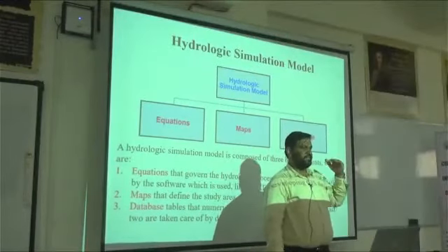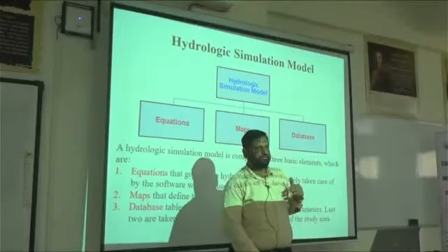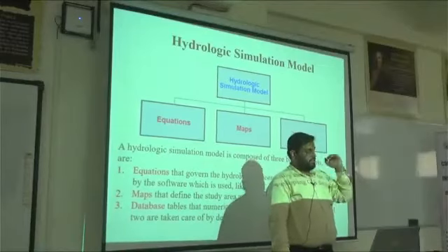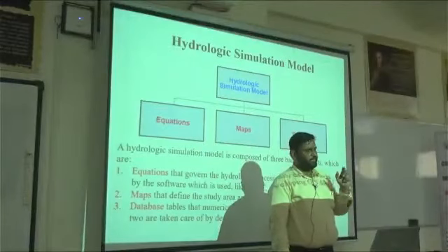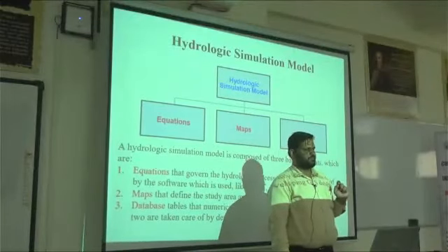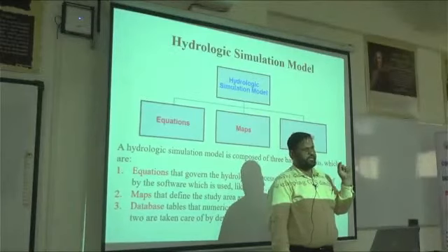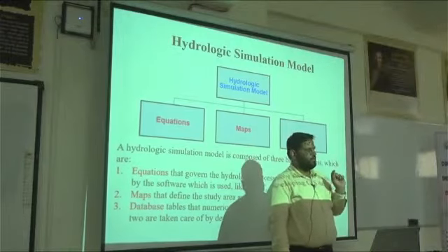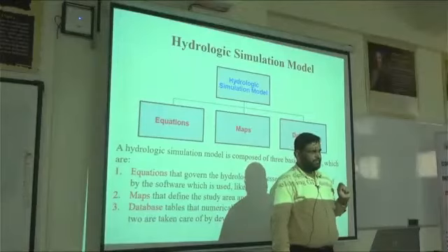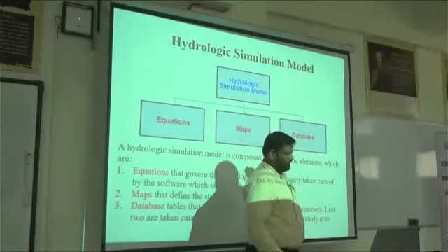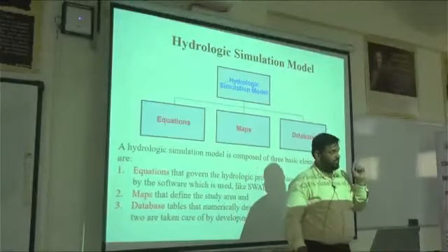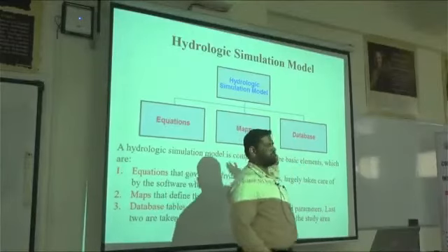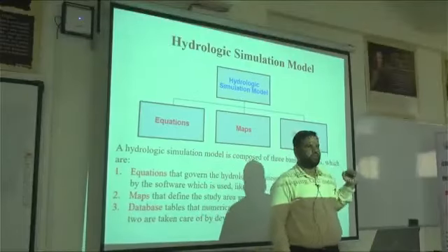The understanding of those parameters is very important, because simply developing a hydrological model is not a very big task, but doing a calibration is a very tricky as well as tedious task. Unless you have complete knowledge of what processes are taking place in your catchment area, you won't be able to do the calibration. That is why you should understand what hydrological models are, what hydrology is, and what water balance equations are. I am not going into details of water balance, as I think they are already covered in the previous lectures of this training program.